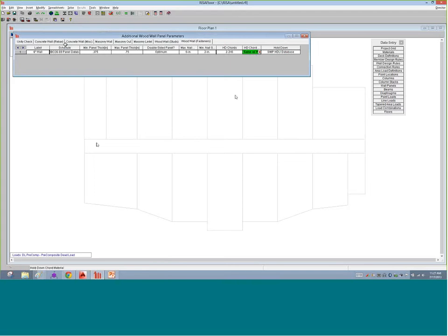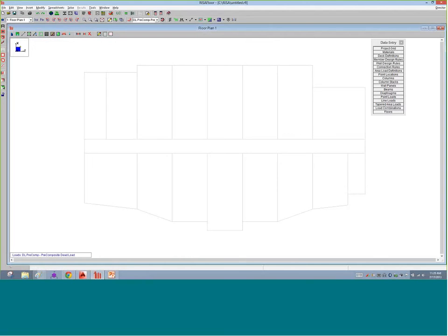So this is kind of my definition laying out for both the studs and the fasteners, as we're calling these. The hold down and the thickness of that panel is what we call the fastener schedules over here. So what I'll do is I'm going to close that down. I could add different walls, several other walls. You just push enter to create a whole laundry list of walls. Typically, you probably would want interior walls maybe differently than exterior walls. I'm going to keep them all using that one first type. I want a 6-inch wall there. But what you could do is you could add to that list.